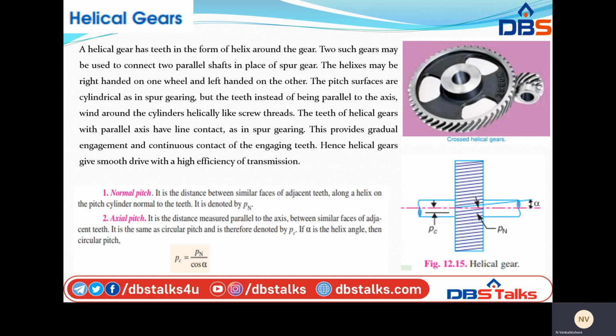It is equivalent to two single helical gears in which equal and opposite thrusts are produced on each gear and the resulting axial thrust is zero. So the double helical gears are used to eliminate the axial thrust, but it is the same as two single helical gears.